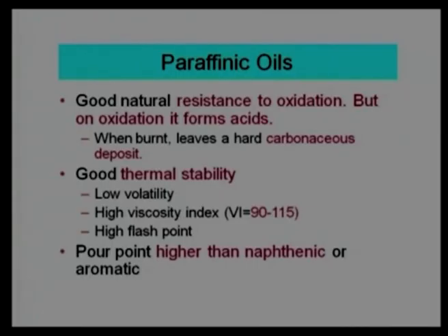So, we select the lubricant for good reason, to reduce friction, to reduce wear, but because of lack of understanding, if we select a lubricant which is not able to sustain the operating temperature, then they will form deposits on the surface, and it is often the case in engines. We find that the oils are making deposits on the surface, and we require additives to wash away those deposits.